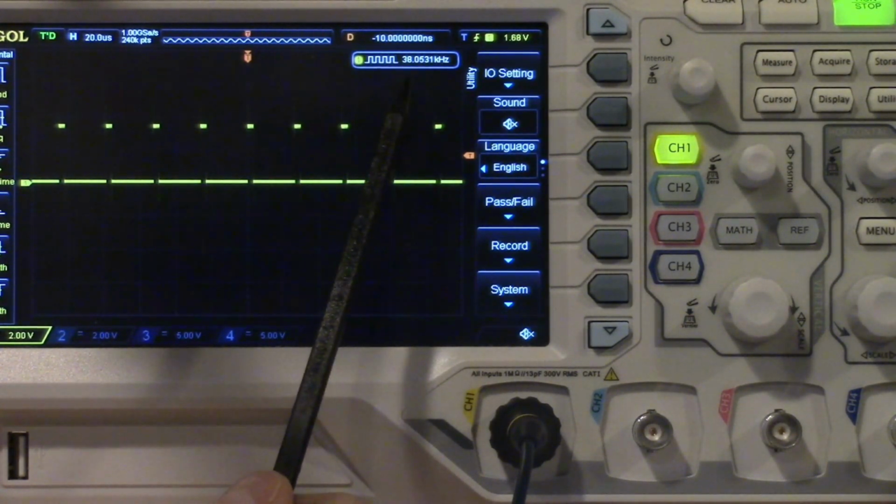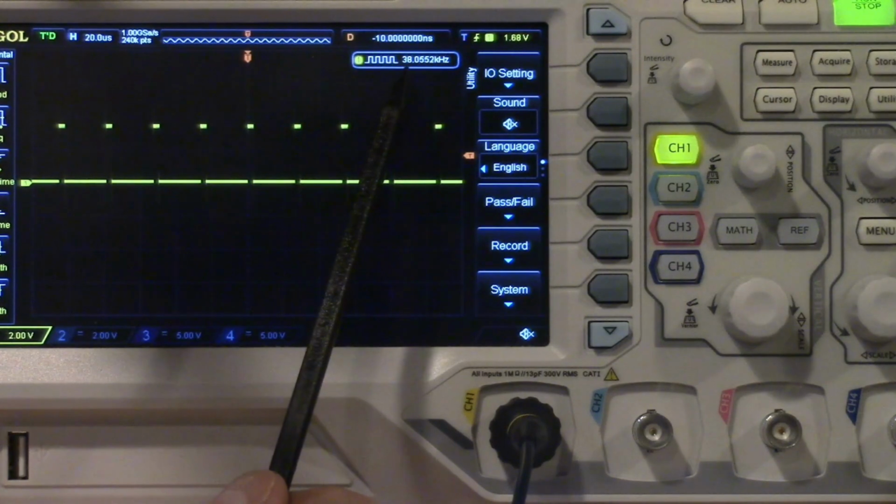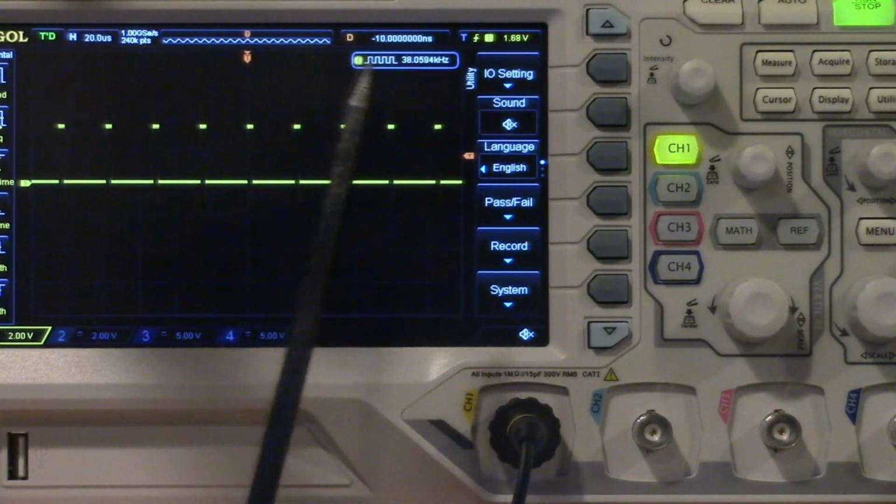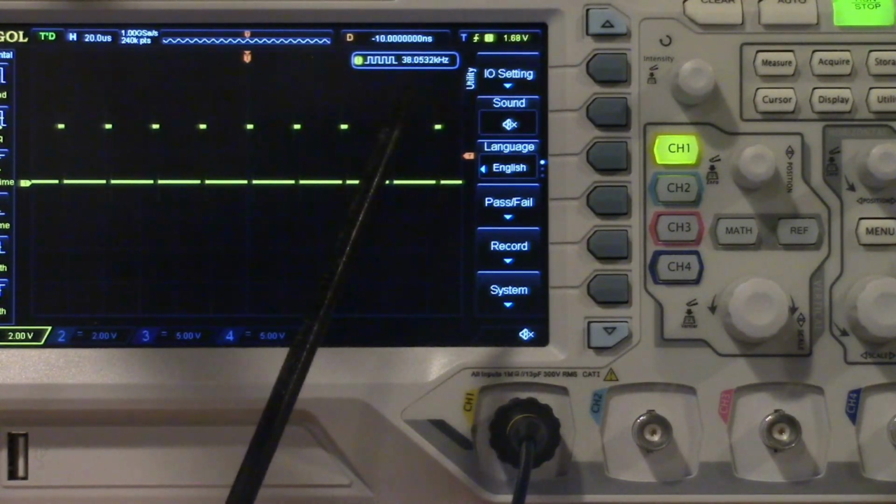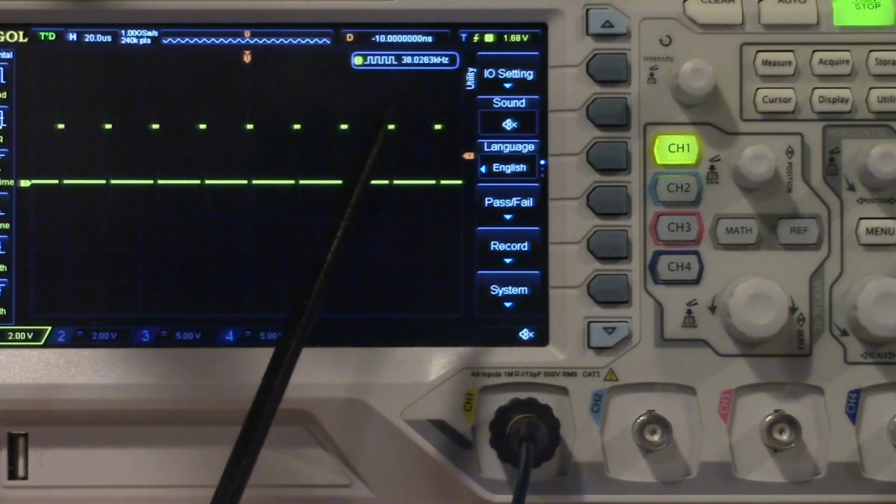So of course, what you can notice on the oscilloscope here is that we are getting a little over 38 kilohertz, and also, disconcertingly, the frequency is changing slightly. So there is some significant jitter in the timing generated by the FPGA, and that's not good for generating video where we want our synchronization pulses to be absolutely rock solid. So we need to investigate why we are not getting accurate timing out of our FPGA. So the good news is I know why we are getting this inaccurate timing, and I also know how to fix it. So let's do a couple experiments to show how we can get reliable timing signals out of the FPGA.